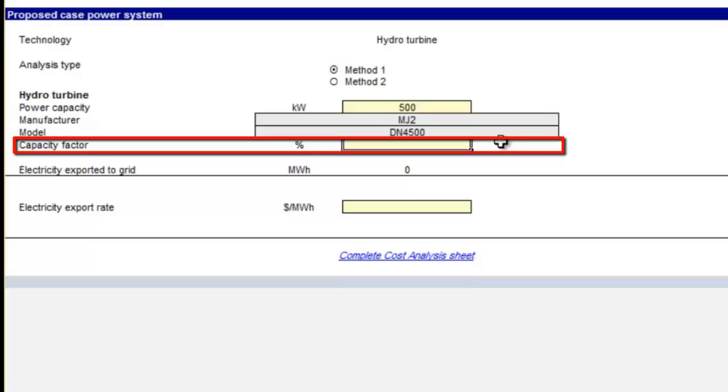If a more complete hydrological analysis was done, it would show a flow duration curve with a high spring runoff and very low summer flow, which would be indicative of a low capacity factor. However, as the river is regulated, a somewhat higher value is reasonable. If the dam had storage capacity, the capacity factor could be higher. However, the operation is run-of-river, so we will enter 60%.